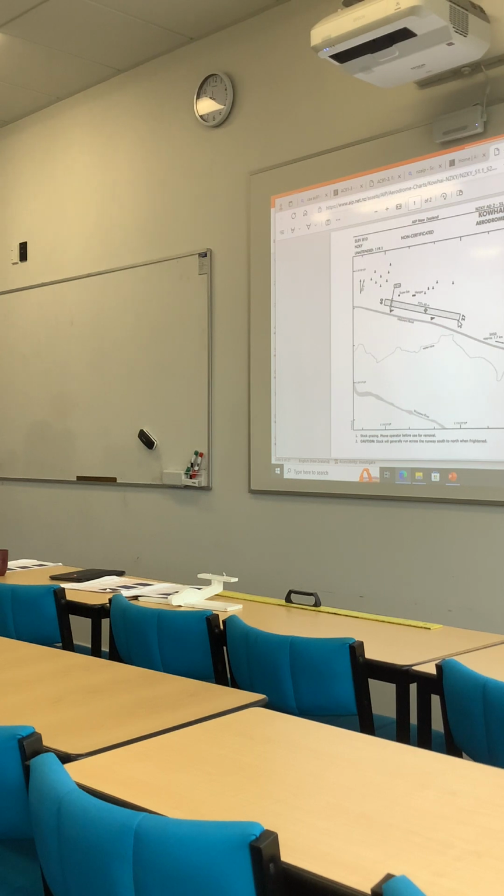So the runway length is reduced, and so the group rating for landing has been reduced. For the opposite runway, taking off, we have to be airborne by that upwind threshold. So it's got a reduced group rating for takeoff, but for landing on runway 27, we can roll all the way to the physical end of the runway, so the group rating for landing is bigger.